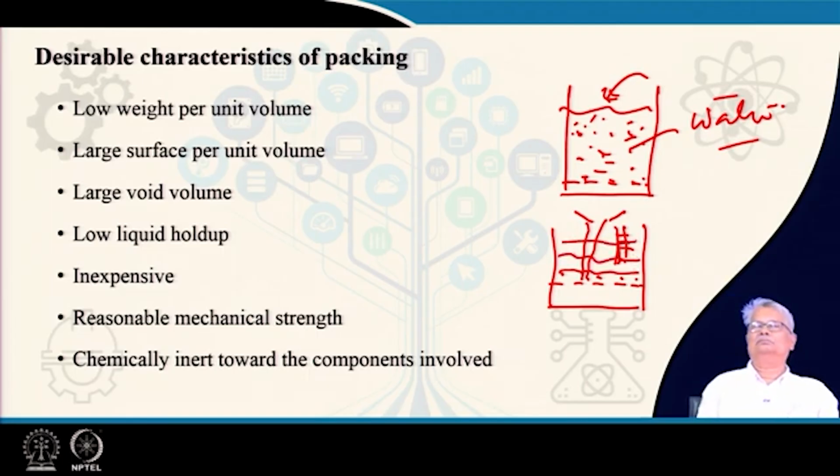So, both are required, and particularly you require a reasonable mechanical strength, because if your packings are dropped from the top, they should not break. So that the impact is less, you usually fill it up with water and let the packing settle down at a slower rate.